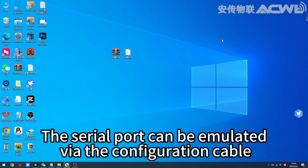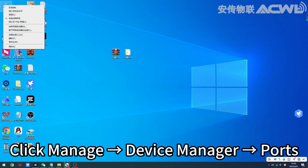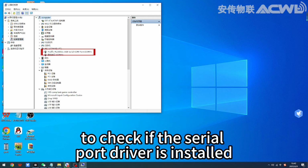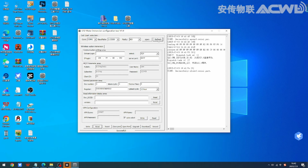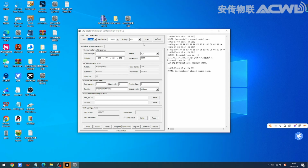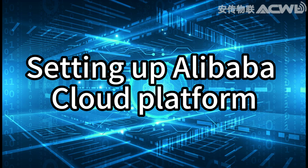The serial port can be emulated via the configuration cable. Right-click This PC. Click Manage, Device Manager, Ports to check if the serial port driver is installed. Port selection. Launch configuration tool. Select emulated COM port. Open serial port.